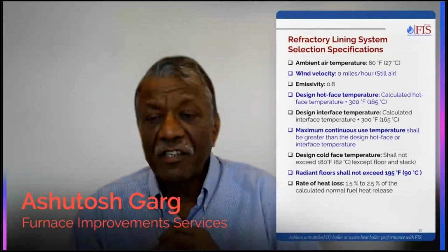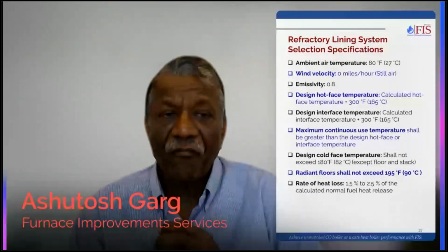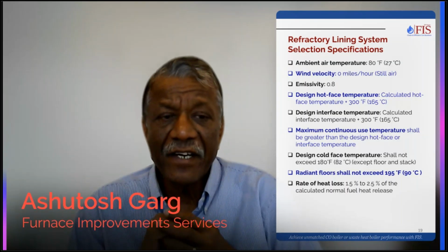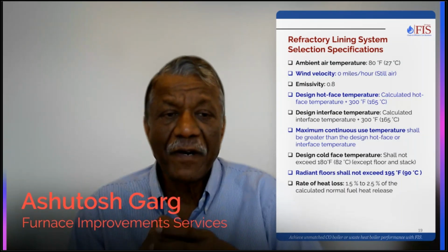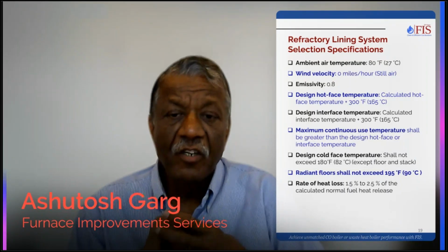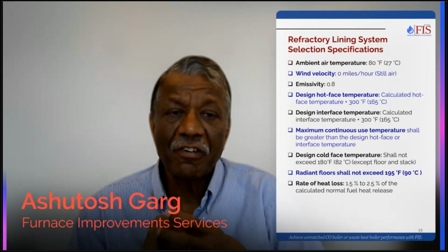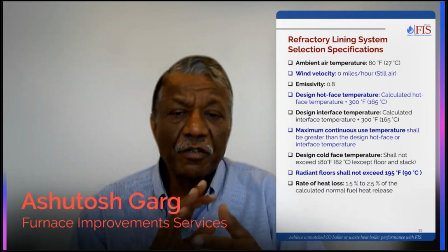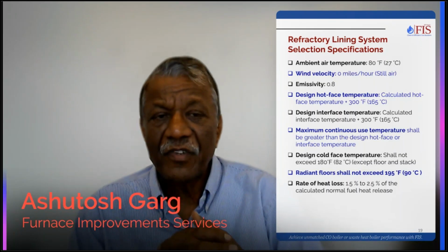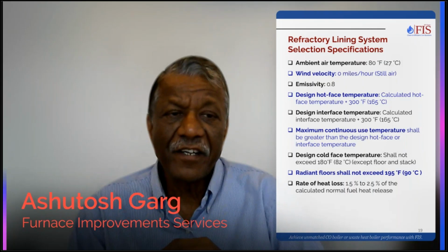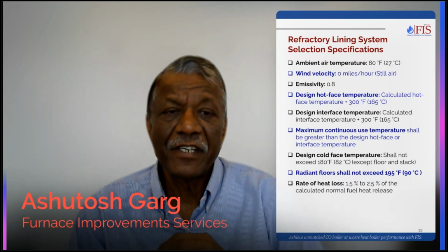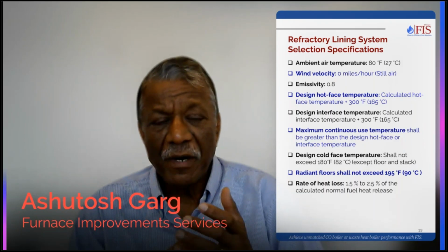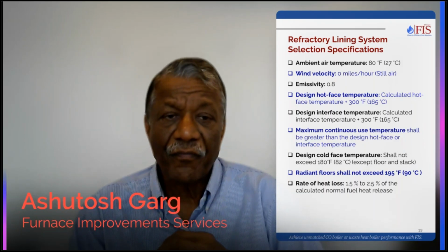So generally, when we are selecting or designing refractory, we have a standard developed by API to be used for heat loss calculations. No matter what your ambient air is, you generally use about 80 degrees F or 27 degrees centigrade as ambient air. Wind velocity is 0 miles per hour, still air.